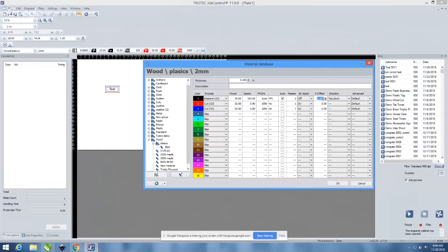Sorry, we just have a quick question. So it's okay to have air off and nozzle on if you're engraving, but air on, nozzle on if you're cutting? If the piece is small, then yes. If the piece is large, like for instance, if you're doing a full quarter sheet of engraving plastic, I would take the time to do the engraving without the nozzle and without air, and then go back as a separate job and do the cuts with the nozzle on and the air on. If you try to engrave a full quarter sheet with the nozzle on and no air, you're probably going to get a significant amount of debris on the lens, so that should be avoided.